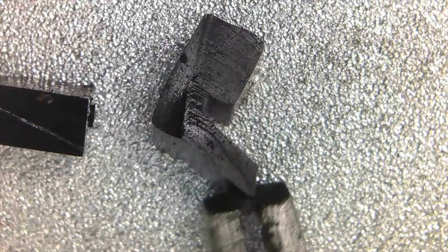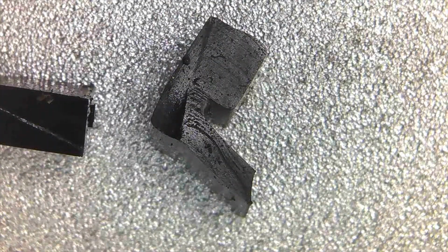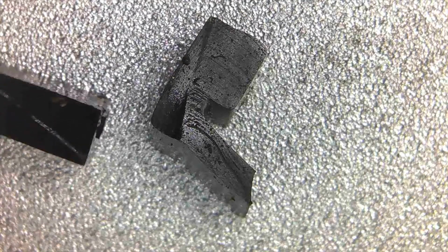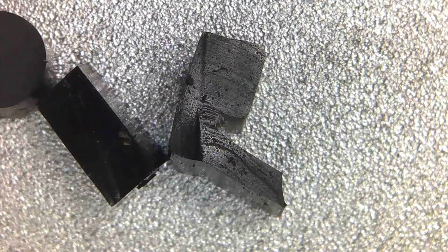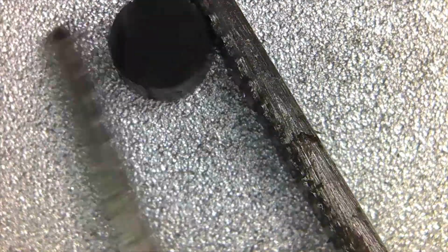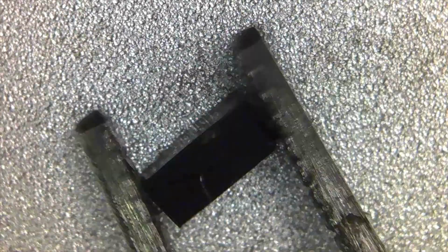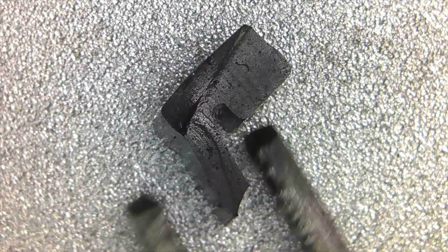And a good rule is once you get that piston in the bore, you should be able to grab it and rotate the piston around very easily if it's a lip seal. Now, if it's an O-ring or a square cut seal, it's going to be pretty difficult to rotate in most cases. So again, we have our O-ring type seal here, and then we have our square cut seal, and then this last one is a lip seal.